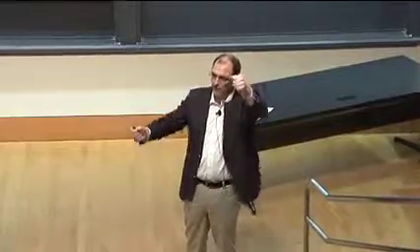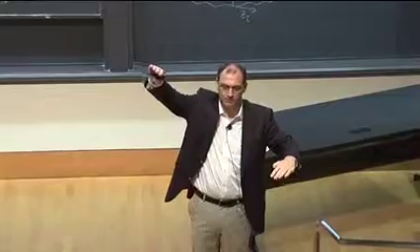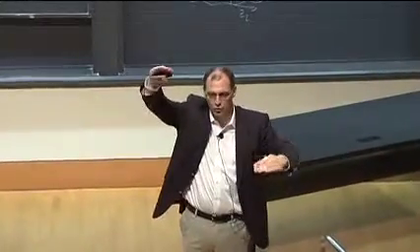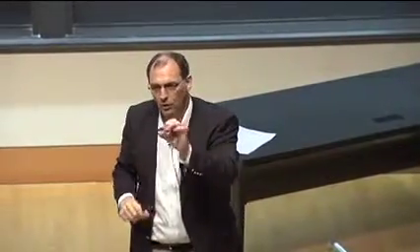Okay? If I have a large eddy like this, it has from left to right a certain change, and that's a large change, let's say, of the temperature or of the velocity. And because it's large, the gradient is relatively small across this. But now, if I break this up into smaller and smaller pieces, then the length scales become smaller, and it turns out the gradients become larger and larger.